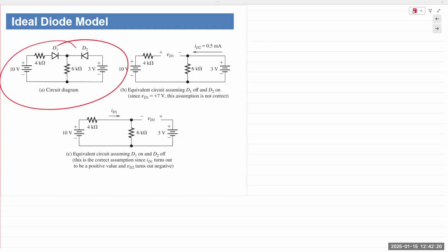The question being asked here was, if we treat an ideal diode as a short circuit, how could the voltage be different at the anode versus the cathode? And that's exactly the point. If the diode is a short circuit, then the voltage at the anode and the cathode is exactly the same, right? So the potential difference between the two points is 0, hence VD is equal to 0.